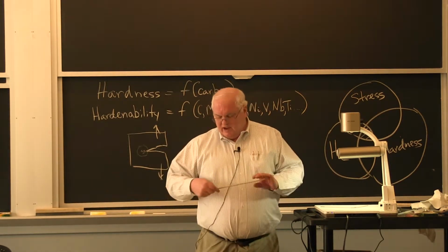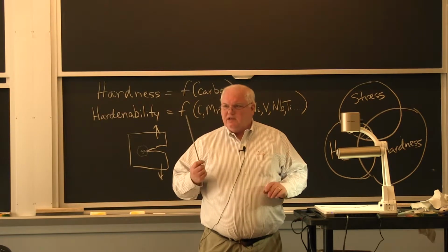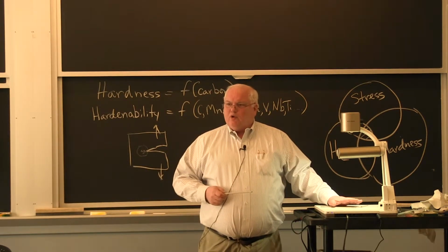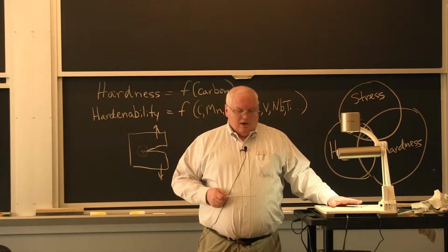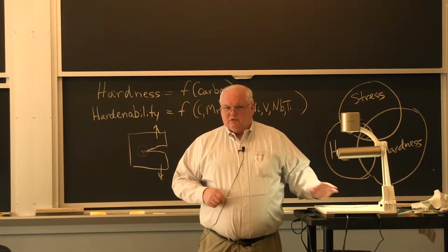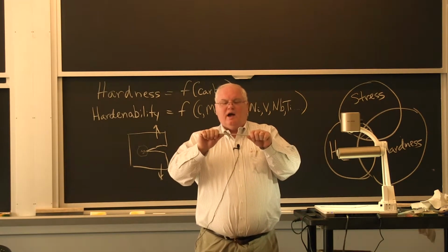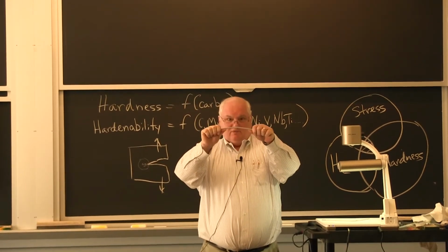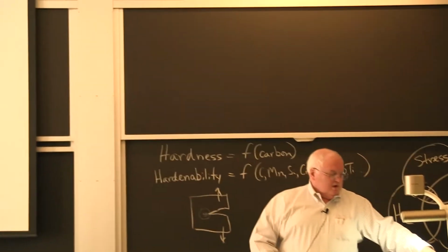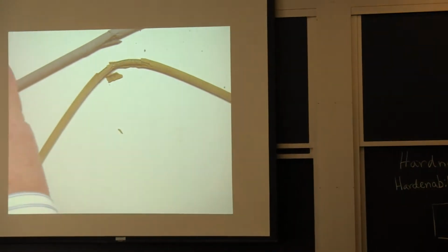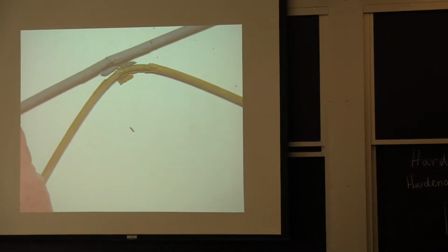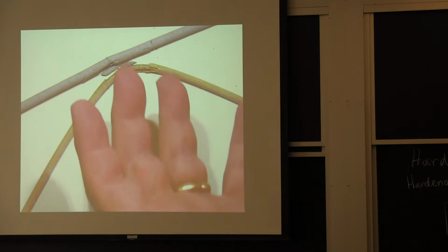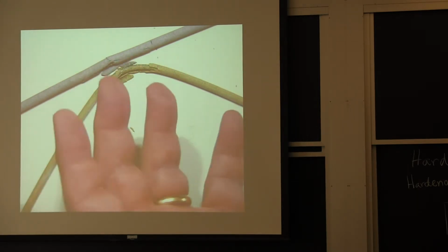If I take a 7018, now unfortunately these 7018s, these were baked at about 400 degrees Fahrenheit to get rid of most of the moisture. These were baked at a higher temperature, but these have been sitting around in the air. And this one, well, I got about 15 degrees before it started flaking off. Okay? And that's because it's basically a brittle, glassy coating.